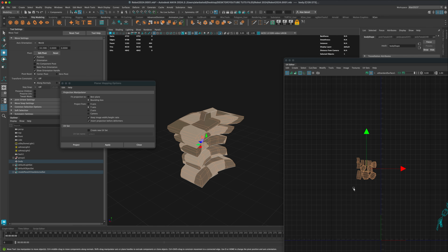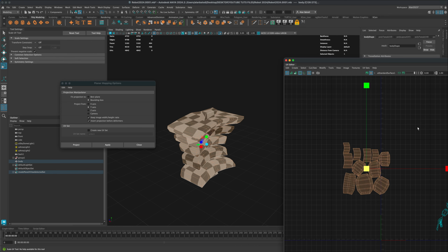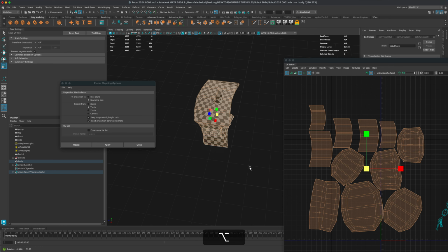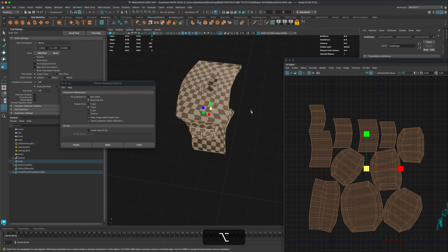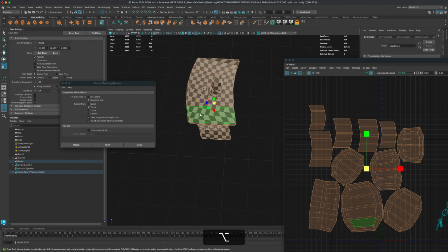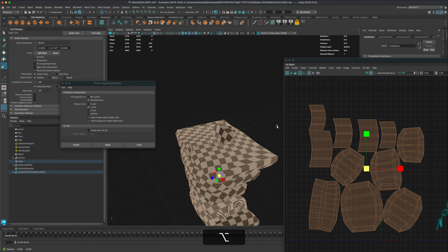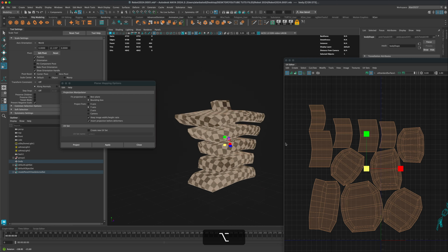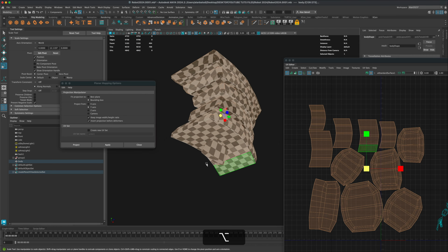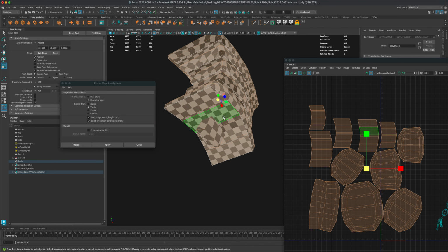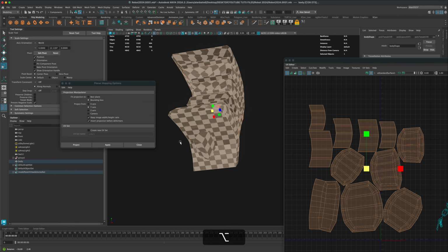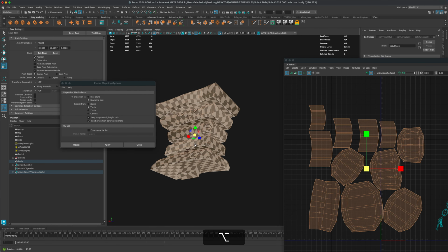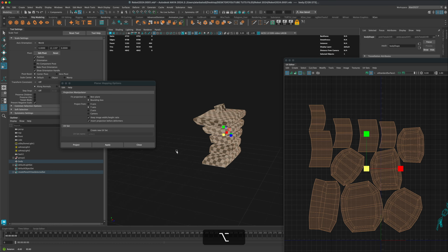And for example, if I grow this up, you can see what I'm talking about, right? So most of the boxes need to be the same size. So like this right here is being stretched, and technically, that's not very good. If you look down here, all of the textures have perfect grid pattern. So that's how you can quickly check and see if you are doing a nice job unwrapping it.